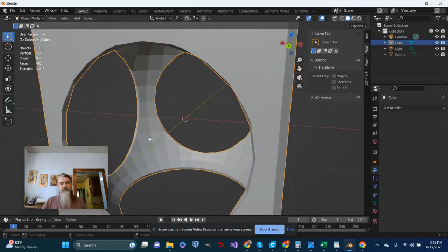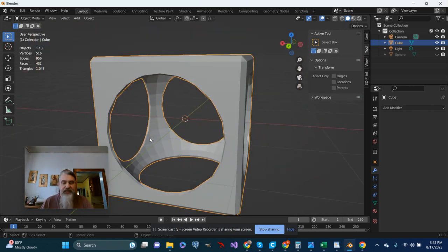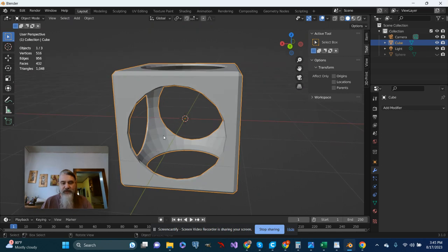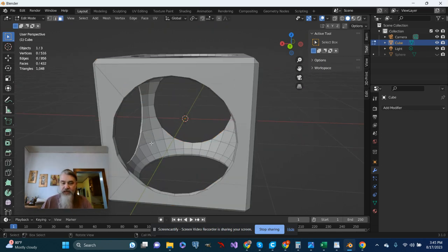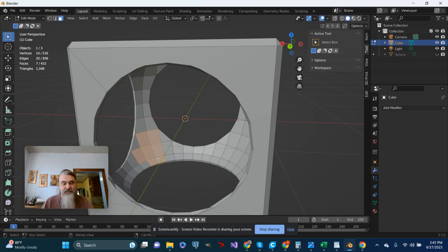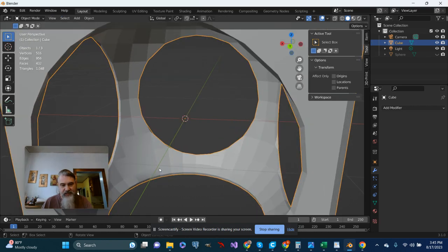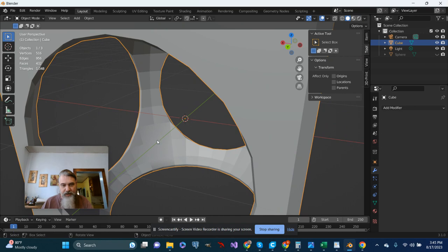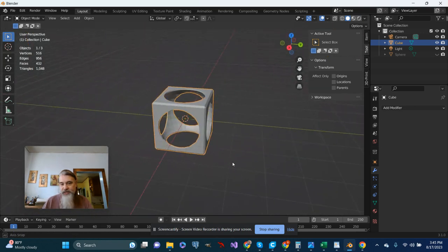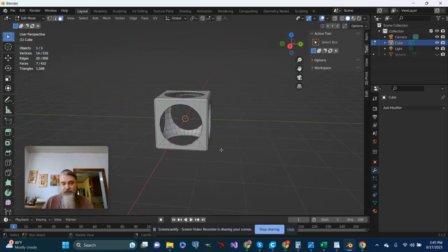Other option would be that I can apply it surface by surface. If I tab and go into edit mode and I select specific surfaces that I want to, I can likewise go to the face and I can shade smooth. When I tab out, you see that that's been applied to this general area. Now, of course, this can get really putsy, but let's just go ahead and play with this.